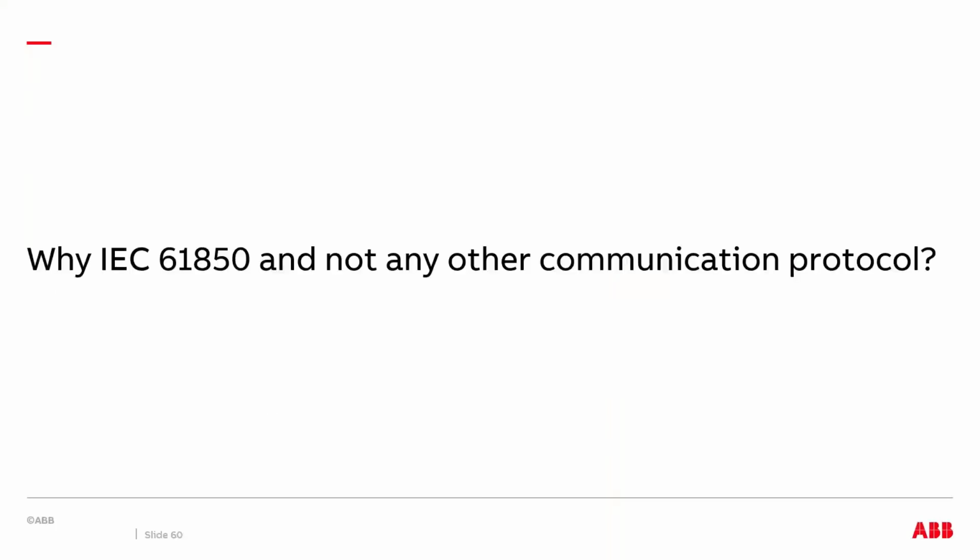So why are we using IEC 61850 and not any other communication protocol like Modbus or TCP/IP or DNP3? Because IEC 61850 is an open and global standard for power system application. It actually defines all the objects that are there in your single line diagram.